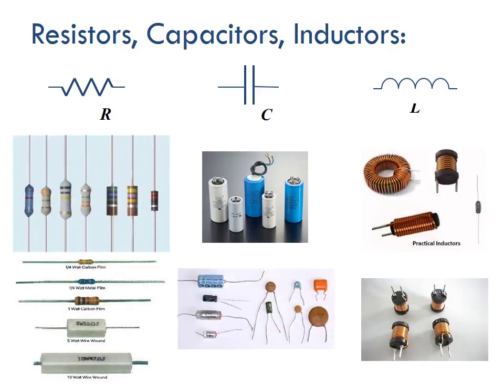So inductors generally, as a rule of thumb, when we're trying to use RC and L circuits, if you're trying to do a smoothing circuit for some kind of filter or whatnot, we generally try to use capacitors and not inductors because capacitors are easier to produce in different values. Inductors, since there's a coil there, and the coils can be spread a little bit differently, are a little bit more expensive, and they're also not always as reliable or as exact as capacitors. So in general, if using for filtering circuits, we stick with the capacitor-based version, although keep in mind inductors can be used just as fine.